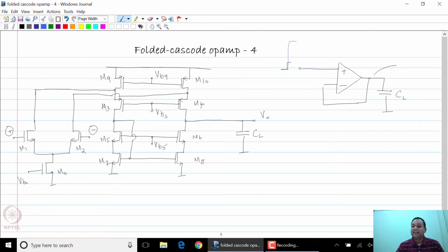So when the input step gets really large, the output current of the op-amp cannot support such a large rise time, and there is some maximum output current that the op-amp can deliver, and at this stage the output rises linearly. More importantly, any larger input step will not allow the output to rise faster than this ramp. This is called the slew rate of the op-amp.